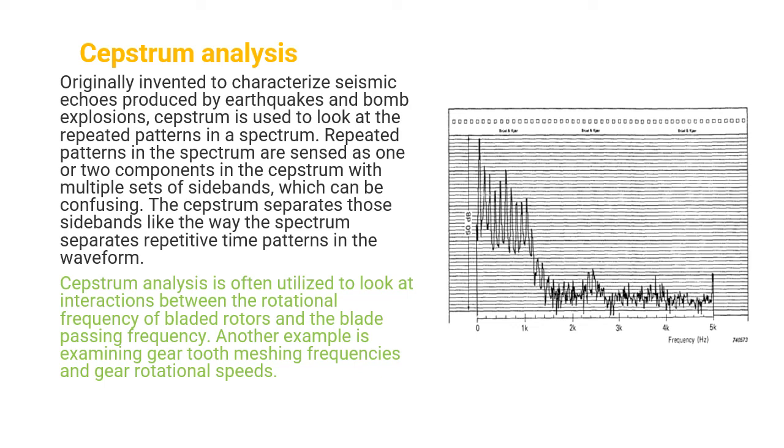Cepstrum analysis is often utilized to look at the interaction between the rotational frequency of the bladed rotors and the blade passing frequency. Another example is examining the gear tooth meshing frequencies and gear rotational speeds.